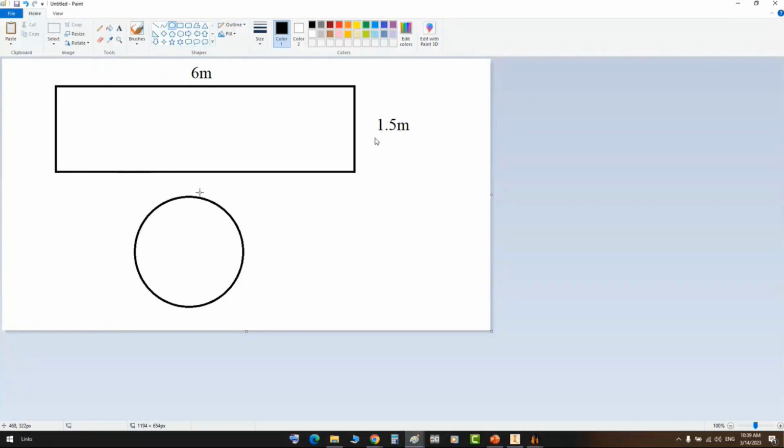When you roll this blade to get the shell diameter, if the total circumference length of this shell is more than that value, SEG will automatically calculate that and detect that you may need another piece to complete the circumference of the shell. Let's try that.